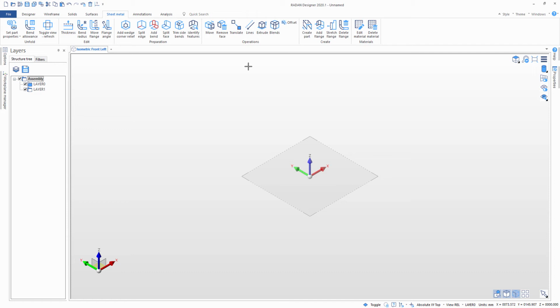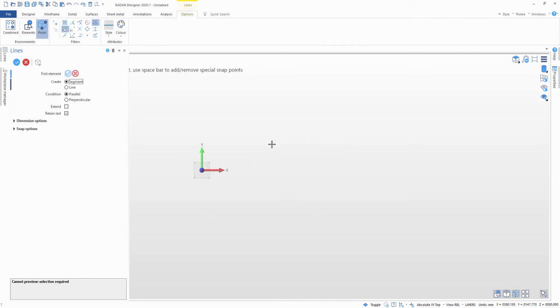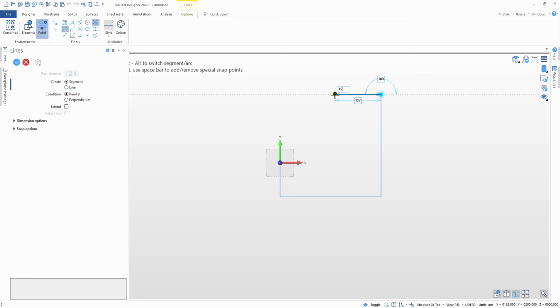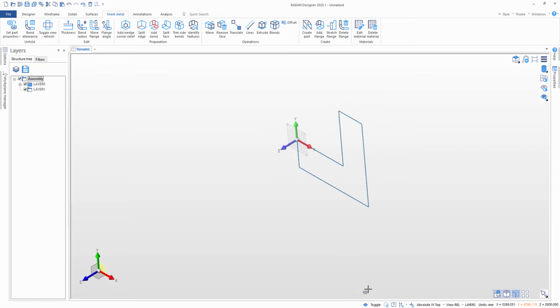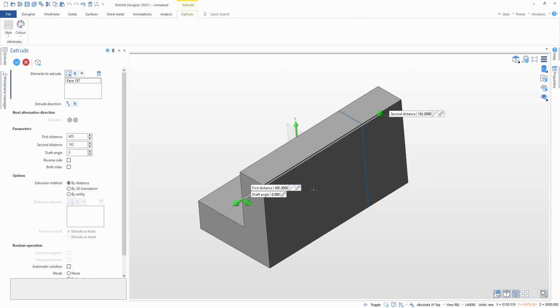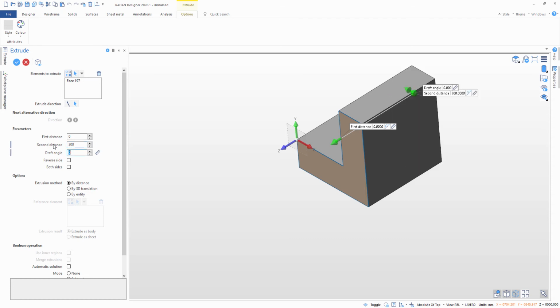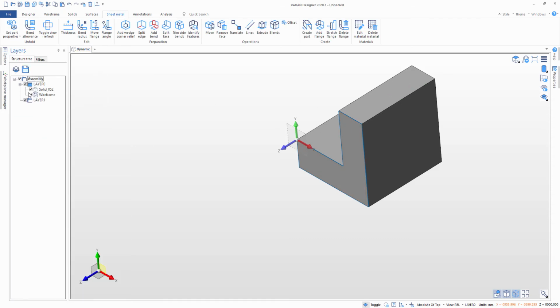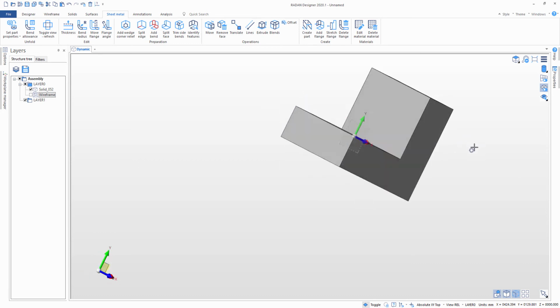a sheet metal user perspective. Okay, so maybe I'll start from creating a solid model. So I'll create roughly something like that, 100 by 300 by 300, say by 100. I'll just drop it here and close it. And now I will extrude this model by, let's say, 300 again. So we have a solid which looks like this.